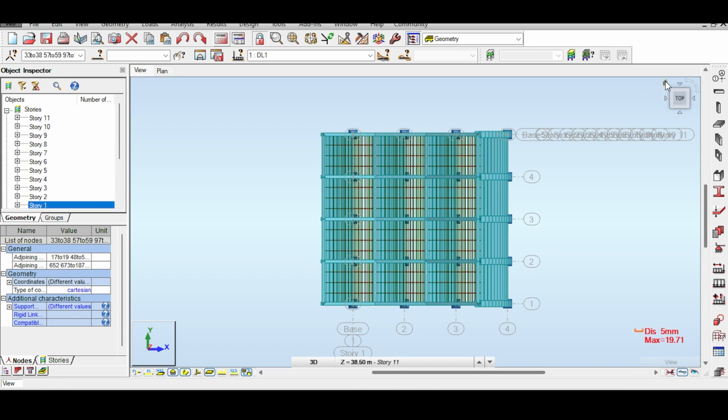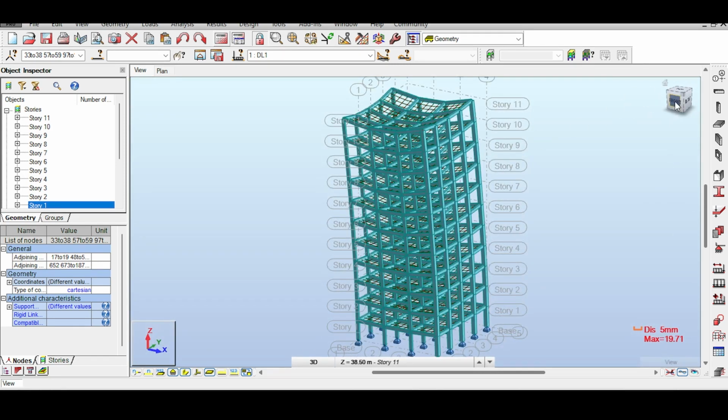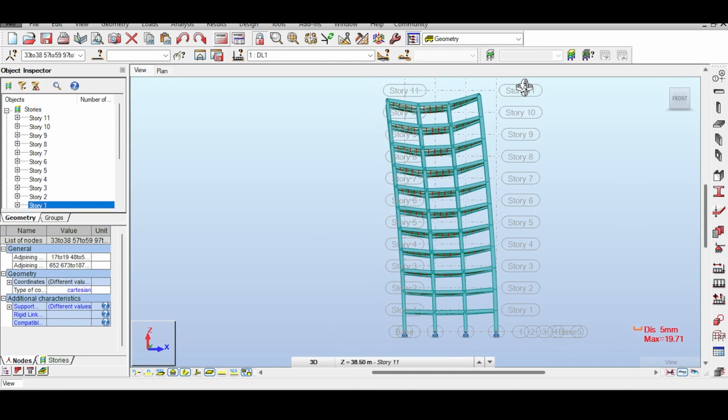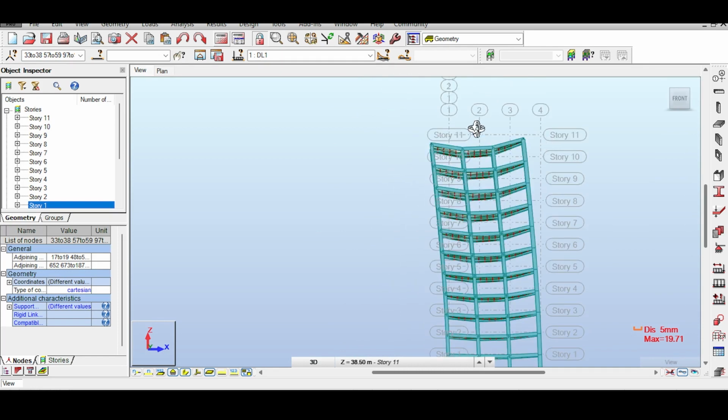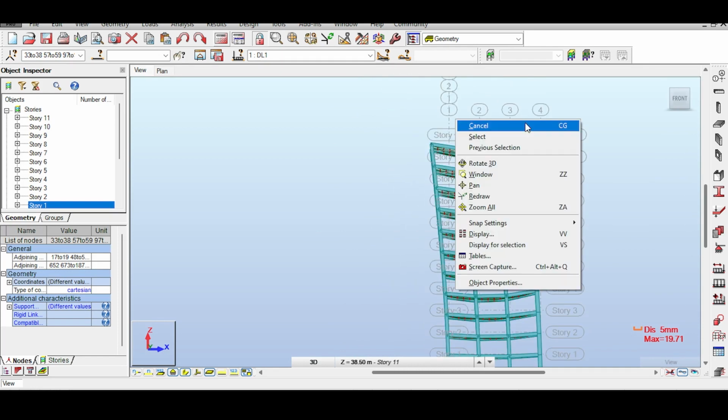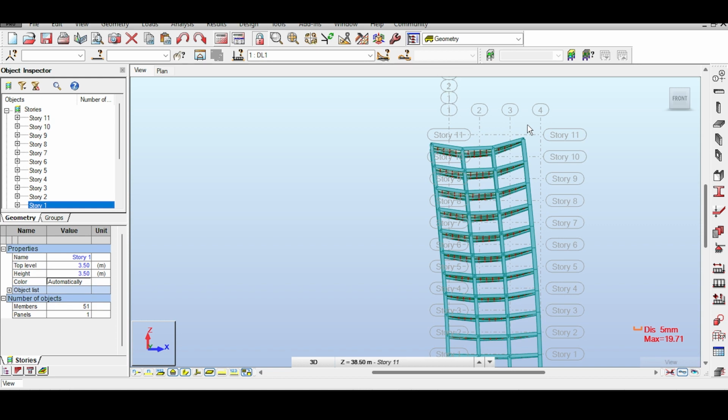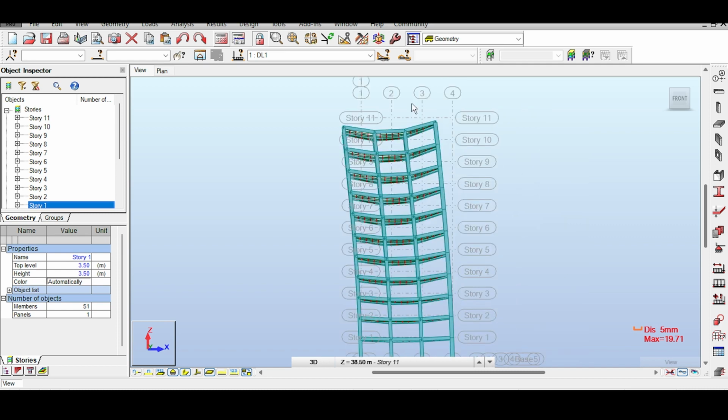Okay, now this should make sense, and allow me to show you what happens now if I remove the connection between the beams and the columns. How do I do that? By releasing. What I'm saying is that another reason why the structure leans, so the structure is leaning to the left not only because the vertical stiffness is different here, but because there is a connection between the columns and the beams. If you eliminate the connection between the columns and the beams, the structure will not lean.